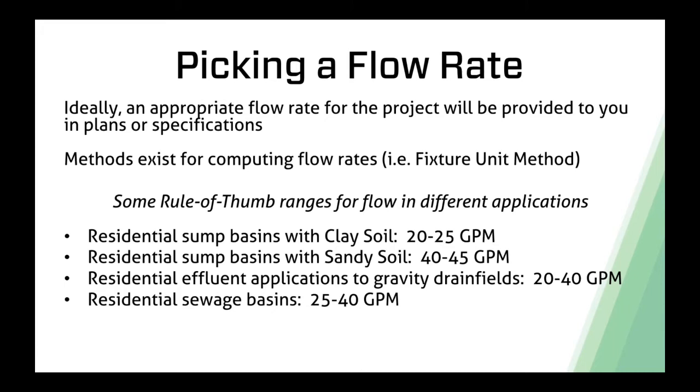But just as some rules of thumb, if you have a residential application that you're trying to evacuate water, let's say out of a sump pit in the basement, if it's a normal size house, not a gigantic mansion, and you had a clay soil, then you're probably looking at a sump pump flow rate necessary in the range of 20 to 25 gallons a minute. If instead of clay soil, you had sandy soil, that flow rate would go up, maybe to 40 or 45 gallons a minute.